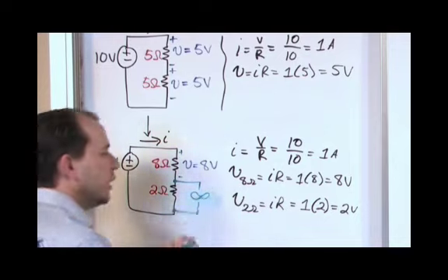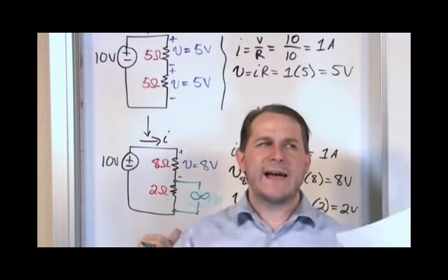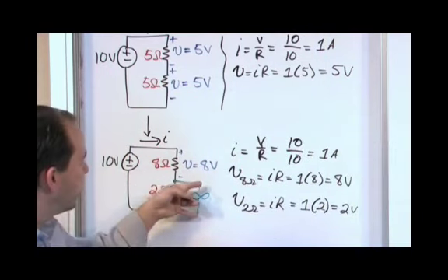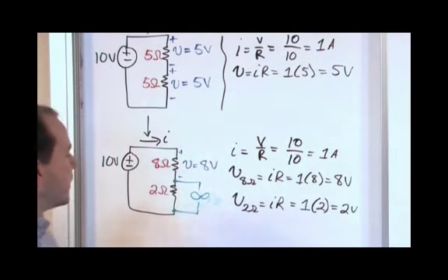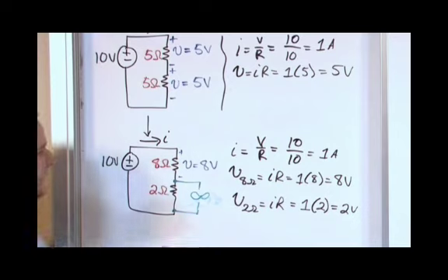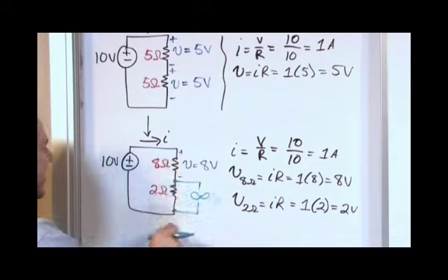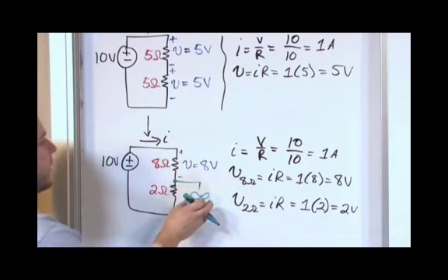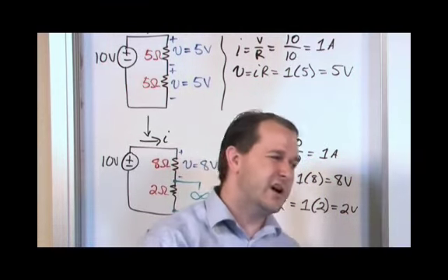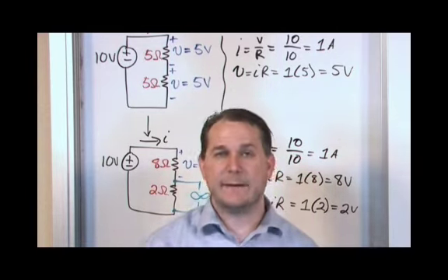So if I connect a load that's a very, very high resistance to my voltage divider, then I haven't really altered my circuit. So I'm still having a pure 2 volts delivered. Everything is cool, right? But if I hook up a load with a small resistance, like maybe 10 ohms, something comparable to what I have here, then these are in parallel. It changes the equivalent resistance, which is going to change how the voltages are distributed, which is going to change the voltage that I'm getting in my load. Which means if my load requires 2 volts, and I hook up a fairly low resistance to it, then suddenly I don't get 2 volts into my load. I get something less than that because I've altered it, right?